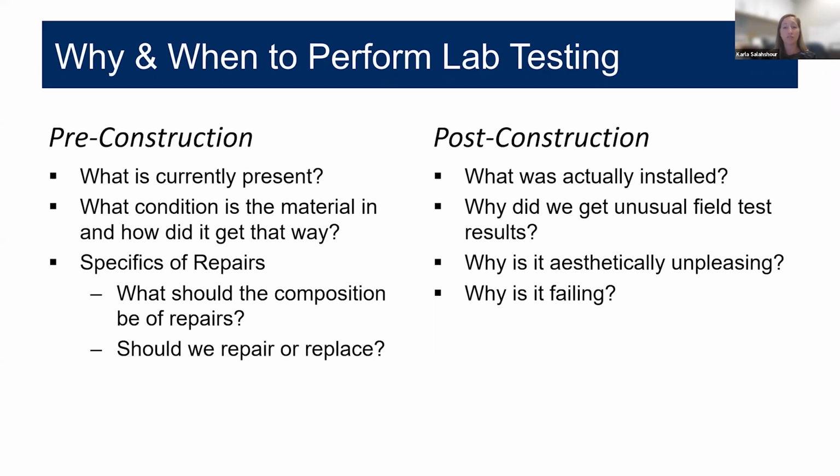And so from a petrographer's perspective, it's important to talk to the person doing the studies, whether it's microscopy or other testing, to really try to develop the goals for the test and the questions that you want answered. So having a clear scope is important. And as is knowing the background of the project, primarily because the lab tests require some level of interpretation. So once we get a test result, what does that mean and how does that relate to your project? And so we recommend early and constant communication between the project team and the lab testing staff to give you the best results.